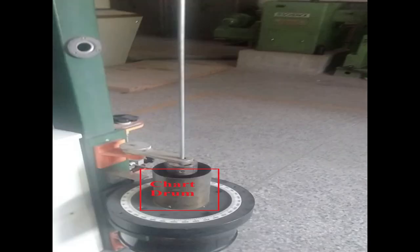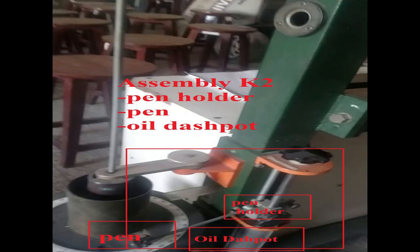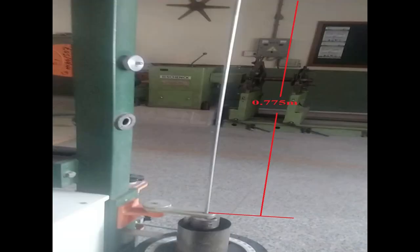A recording of the torsional oscillation is produced by a vertically mounted chart drum which is mounted above the flywheel. Assembly K2 consists of a pen holder and pen which may be adjusted to contact the chart drum and which undergoes a controlled descent over the length of the drum by means of an oil dashpot clamped to the main frame. Various shaft diameters may be used, but due to the location and necessary fine adjustments of oil containers, the length is restricted to approximately 0.775 meters.